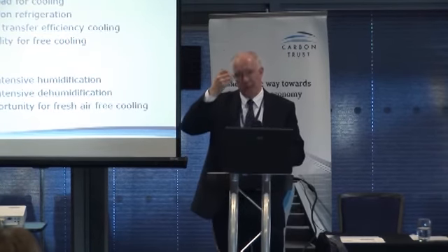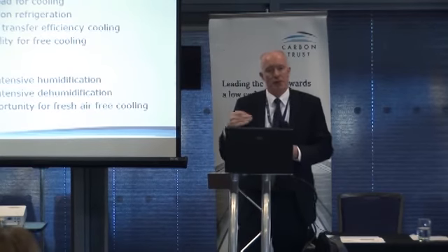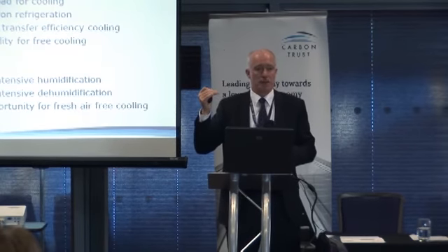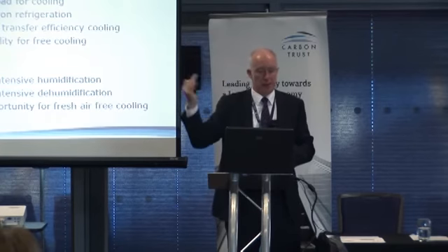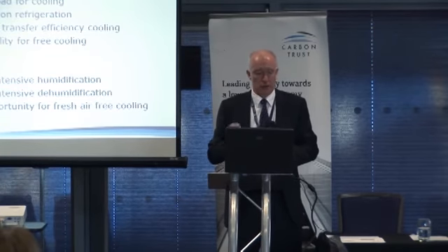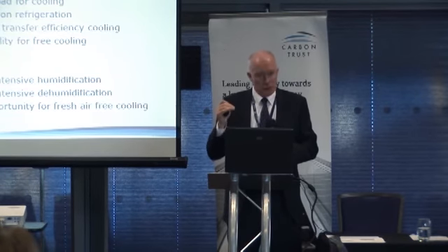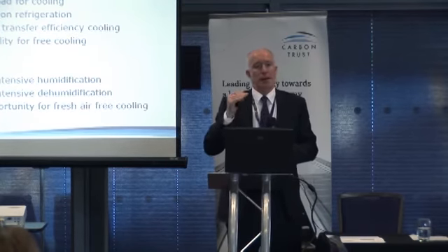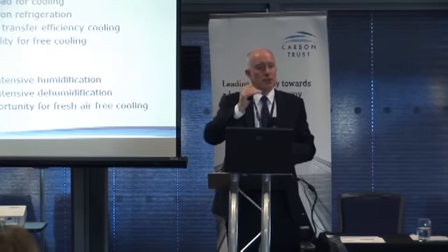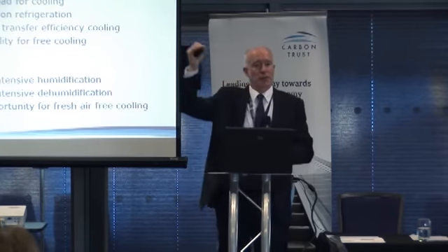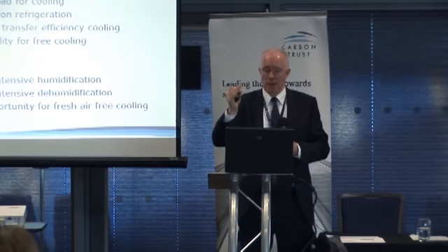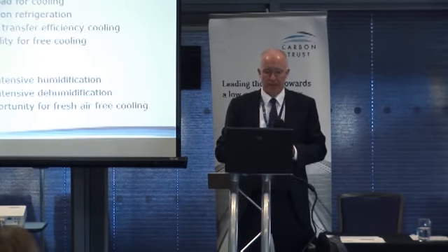Why is the temperature of the computer room so important? Well, obviously, if we increase the temperature in our computer room, we drop the heat load for cooling. So directly, you're going to lose more heat out of that building to other places through conduction, infiltration, etc. Another reason is you improve the refrigeration plant efficiency. If you have got refrigeration plant controlling the cooling of your computer room, as you increase the temperature inside, the temperature in the building is closer to that of the condenser, from condenser to evaporator, and therefore you improve what's called the coefficient of performance. And I'll talk about that in a little while as well.